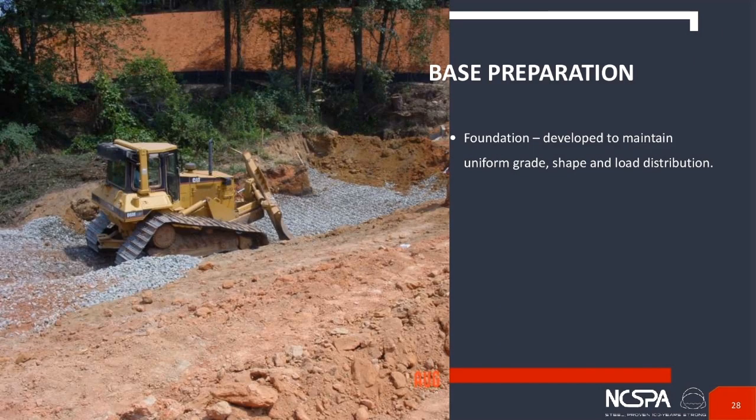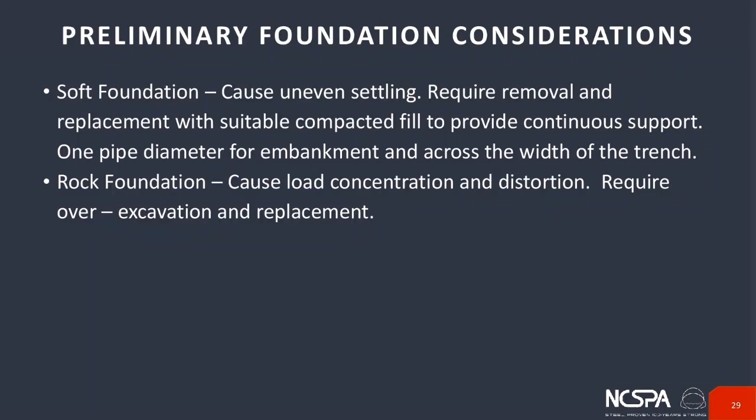Base preparation. This is very important, grasshopper. Like everything else in life, you have to have a good foundation. They allow for uniform grade, shape, and load distribution of the pipe as you begin your backfill preparation. So there are really two types of foundations that we really consider right off the bat. They are soft foundations and rock foundations.